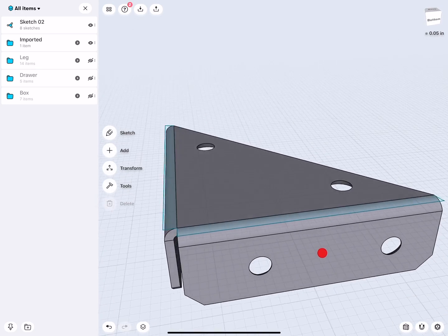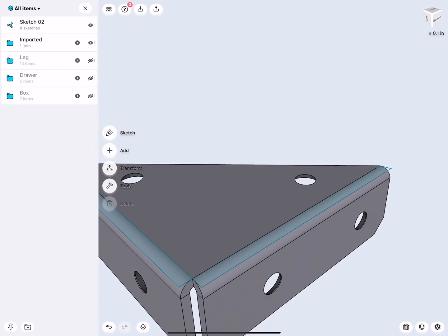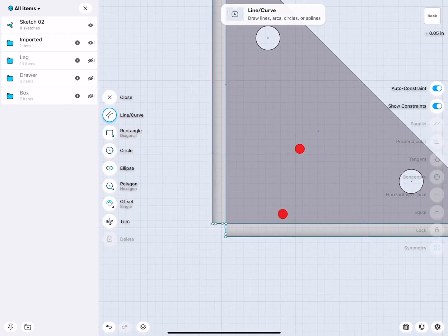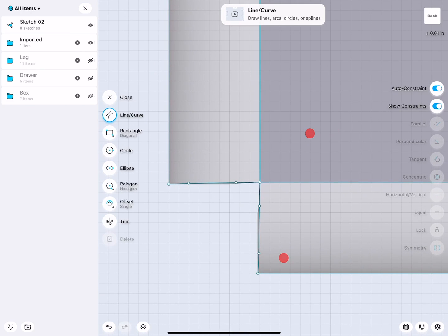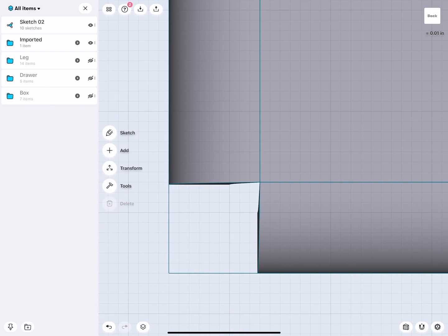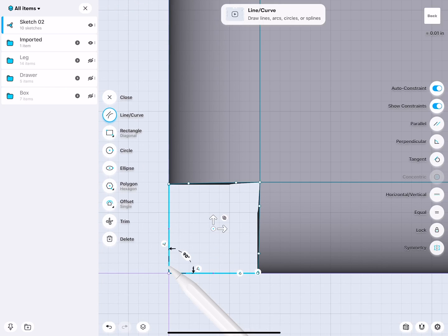If I rotate my view, there we can see we have projected these faces into rectangles. Well, this is very useful because what I can do now, there you see I have some stuff I can snap to. So I will draw a line connected there and a line to there. Very good. So there where these 2 lines meet, that is essentially kind of like the corner I need for snapping.